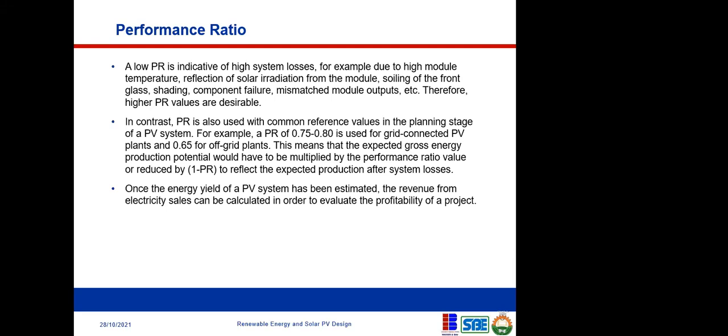If you're using a solar panel rated 300 watts, and a peak sun hour of 5, and you use that to calculate your energy yield for 1 year, that 300 watts assumes your temperature is going to be 25 degrees centigrade and your solar irradiance is going to be 1,000 watts per meter square. How do you know you're going to get 1,000 watts per meter square for those peak sun hours? You're not sure. So just to be on the safe side, you come down to about 75. I don't want to go with the idea of worst case scenario because it could even be worse than that.